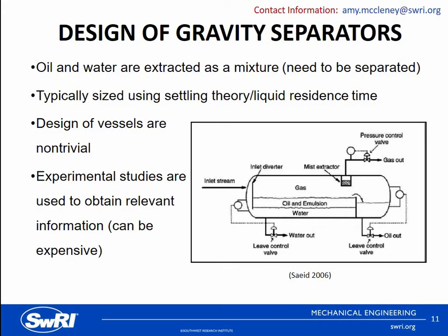However, most of the available data, design guidelines, and prediction models are based on air-water analyses at atmospheric conditions. This can be problematic since the performance of separation systems with hydrocarbon fluids and at elevated pressures is often significantly different, resulting in either an overly conservative design or undersized equipment. Compounding the difficulty is the fact that floating platforms must also deal with severe weight and footprint limitations for separators, in addition to allowing for unavoidable wave motion expected at sea, which has a mixing effect that tends to decrease separation efficiency.